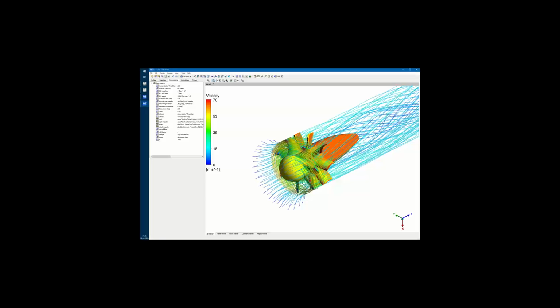If we take a closer look at the hydraulic efficiency, the aerodynamic efficiency of the impeller, you can see we achieve an efficiency of around 90%. If we take a closer look at the efficiency of the complete stage, we still achieve an efficiency of 80%. But of course, we need to meet our specified operation point.